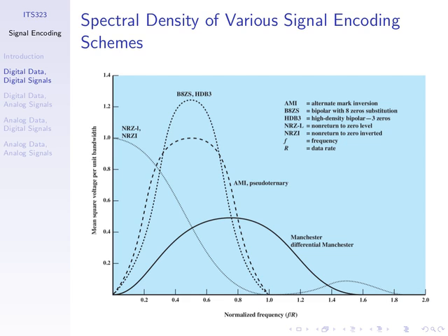We're going to skip over some of these slides. They just show a comparison in terms of the bandwidth occupied by the different schemes. This is the frequency component, so the bandwidth of the signal. We'd like to minimize the bandwidth and avoid signals with zero frequency, a DC component.